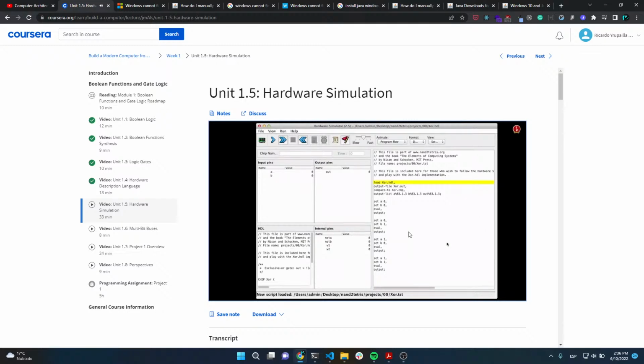And the first command, or the next command to be executed, is highlighted by a yellow bar. We can call it the cursor of the test script. Now, we see that each command ends either with a comma or with a semicolon. And when we click the play icon, the simulator is going to execute all the testing commands until the next semicolon is encountered.